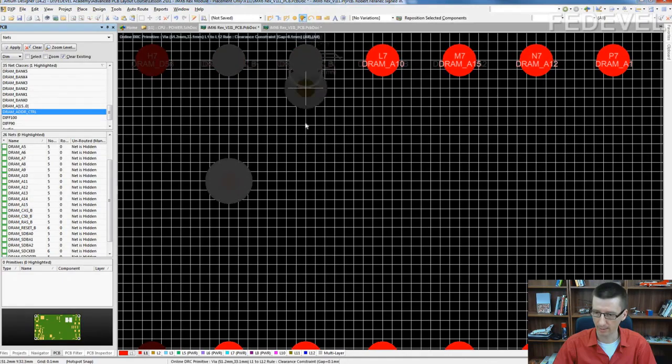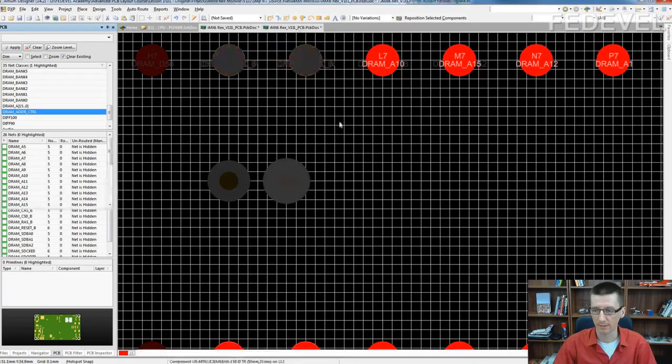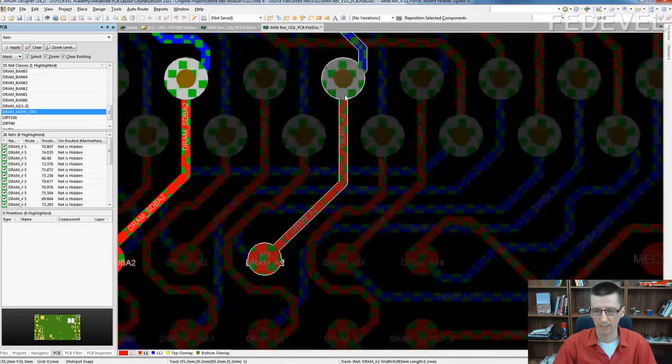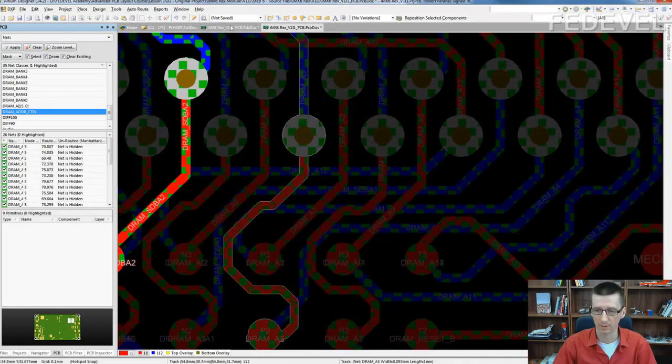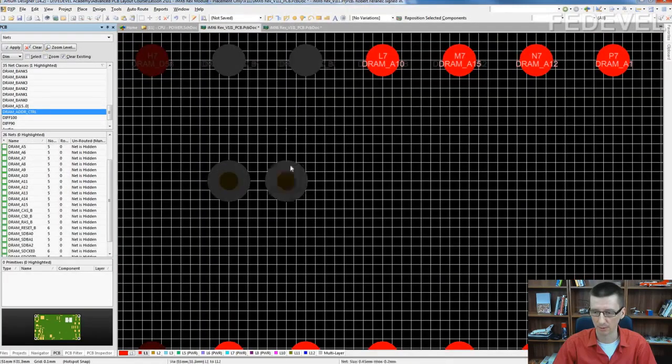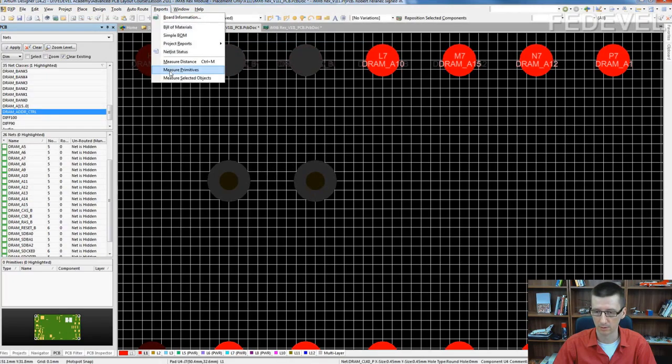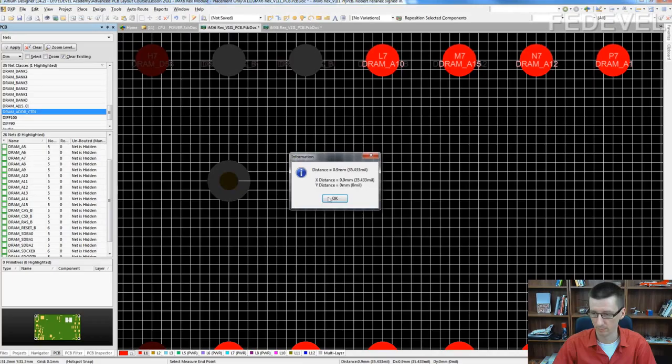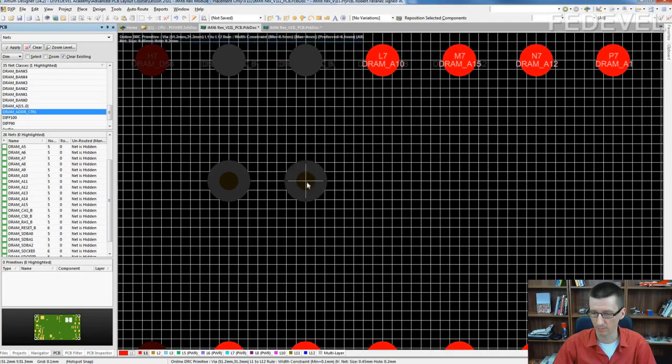Now the second through-hole via. Shall I place it here? Here, here. How far do we need to place this second through-hole via? You need to have space to route tracks between the through-hole vias. The minimum distance where you can place it, you can calculate based on your minimum clearance and minimum track width. In our case, it's 0.8. It's 0.9. I will move it here.